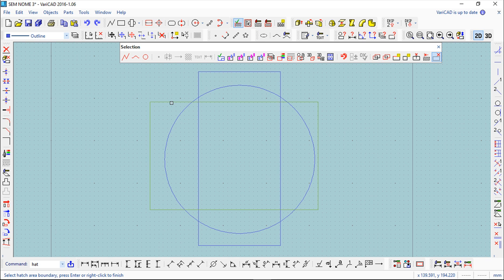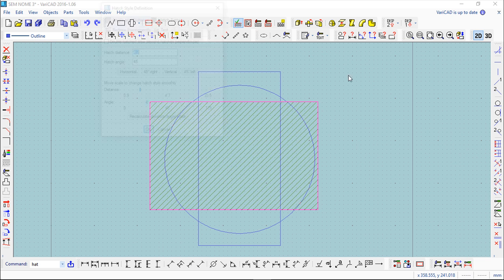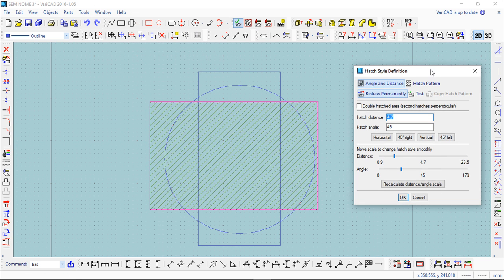Or if I wish to do it manually, for a complex contour, one other option is to prepare the entities previously, breaking the entities to allow me to select all around. Okay, for example, the manual way, I would do something like this and use a pattern.